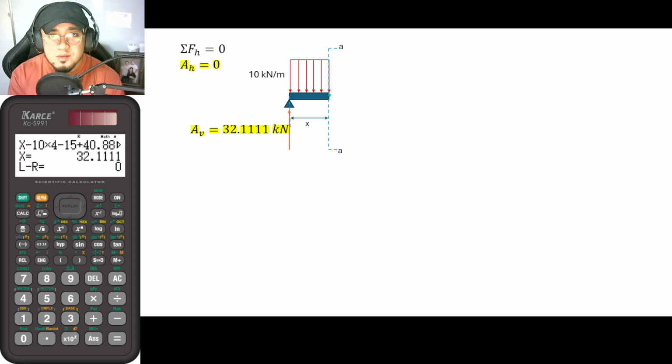So we would now be having an internal force here, or the internal shear, and we also have the internal moment. So you would now be solving for this shear force and moment. And how? In order for you to solve for them, you would now be making use of the static equilibrium equations, such as summation of forces vertical and summation of moments.